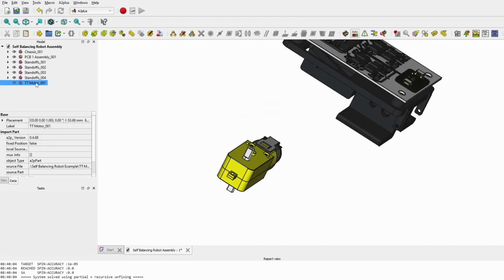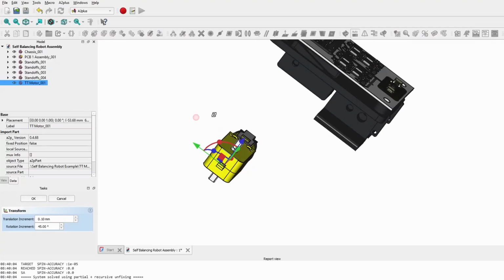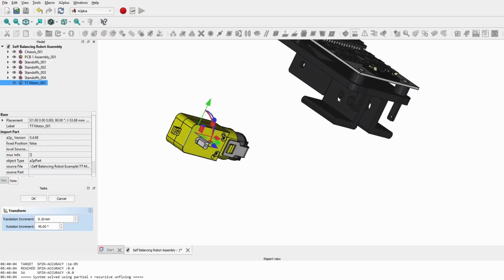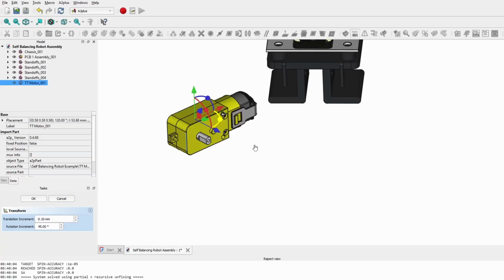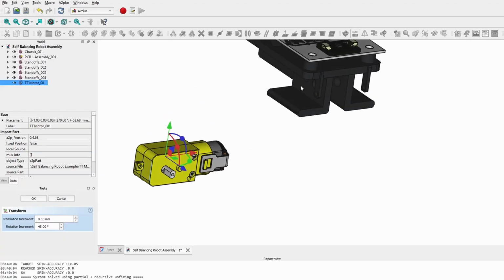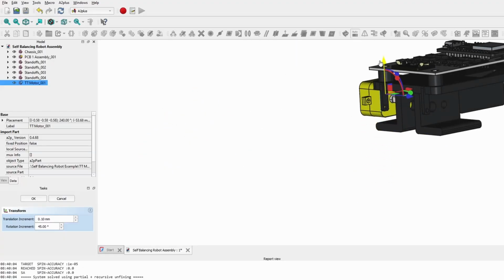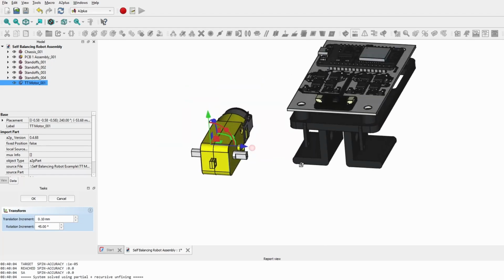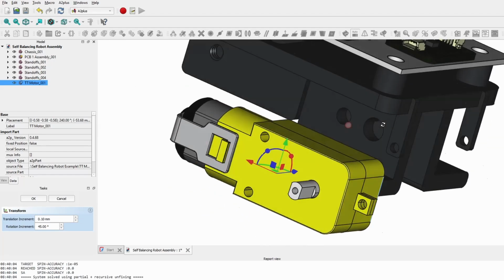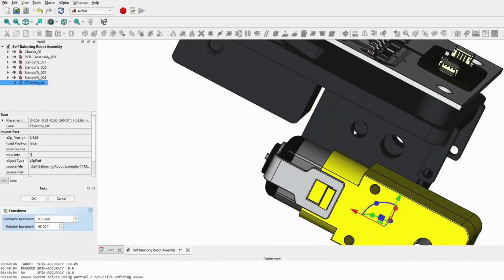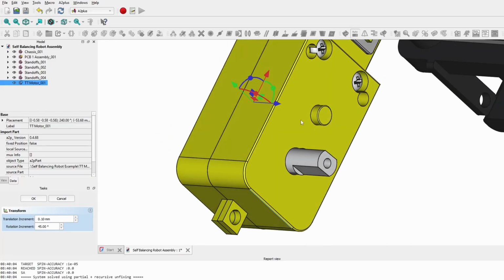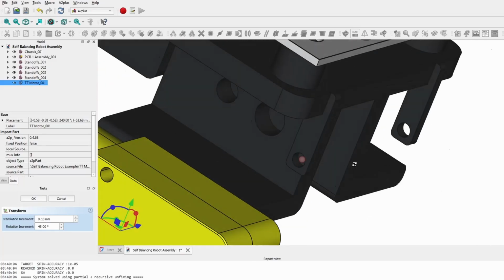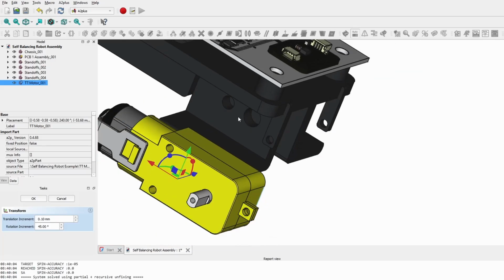Sometimes before you connect things, you need to align them so that they actually come in correctly. What I mean by that is, if we were to align the edges like this, it would not work. You would have to rotate the object so that it is in the direction that you would want it when you merge the two objects together. So in this case, we want this axle and this cylinder to fit into those two holes there, respectively.